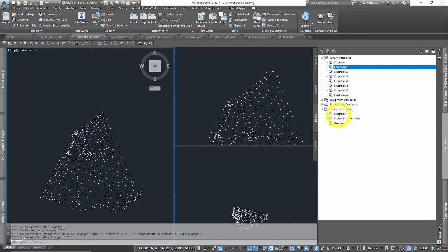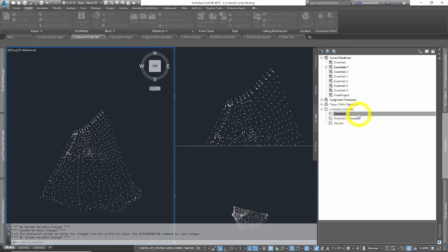Now we want to take off our old junky sample one that doesn't do much for anything. It's just a default one. And you might have to hit refresh on this possibly to queue it up, but I didn't have to. Go to Essentials and select Make Current first. Now right click and select Edit. We're going to look inside of this line work code set.